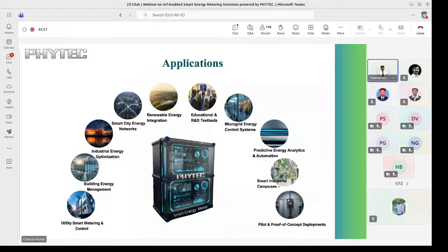Once the NIC card gets the data, it will send the data over the RF to this NIC card. Then the meter will get the data through UART. The DCU will get the data, then over Ethernet it will send it to the head-end system. For the head-end system, we have this dashboard. So you see, this is our dashboard for our RF mesh technology, this RF mesh demo.